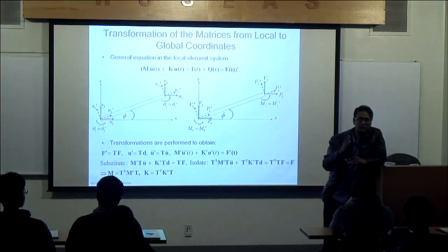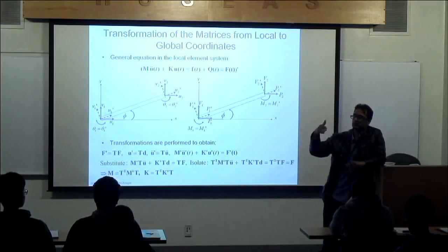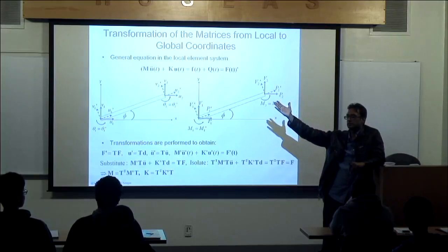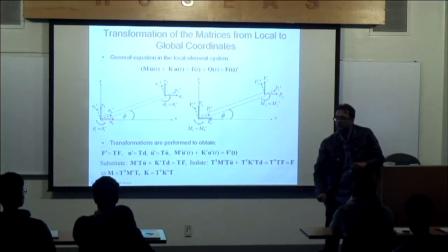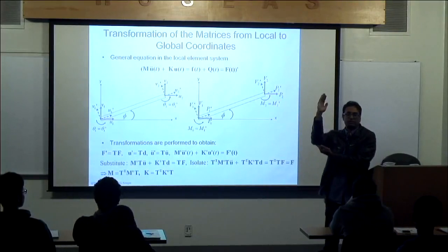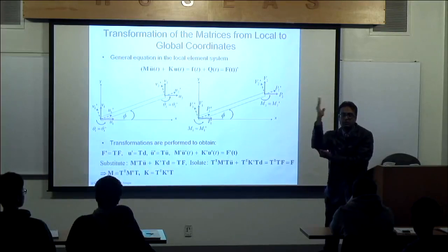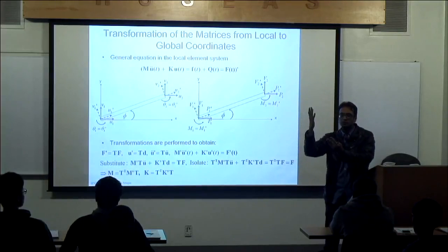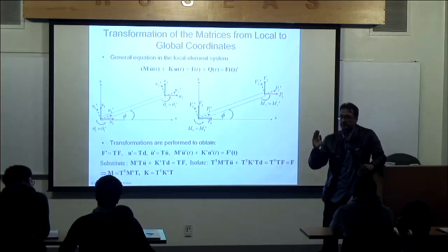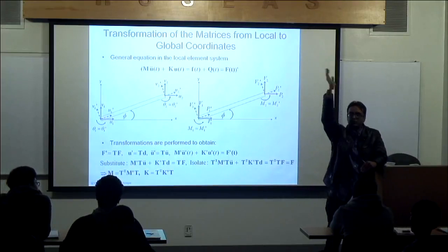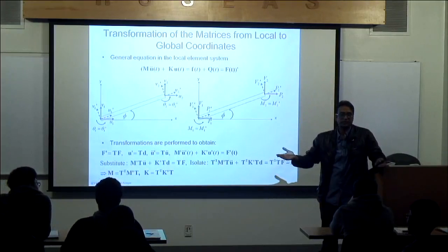In a launch vehicle, for example, we'll calculate modes up to 70 hertz because everything above 70 hertz is not important. I don't expect my launch vehicle to deform jaggedy all the way from top to bottom. I expect it to be bending in the first mode, the second mode, the third mode, a torsion mode, maybe some other modes, but I don't expect a launch vehicle to have like 16 waves from top to bottom, right?